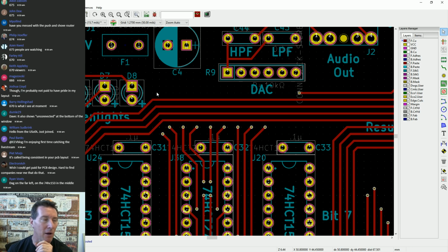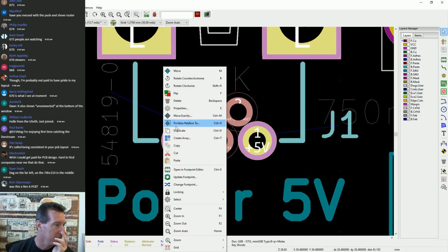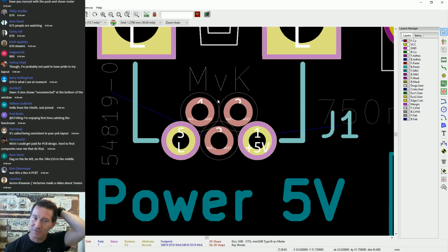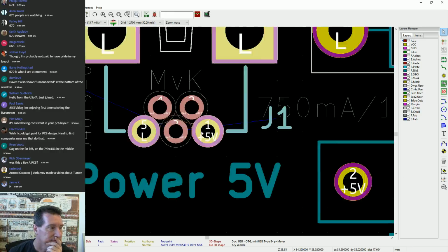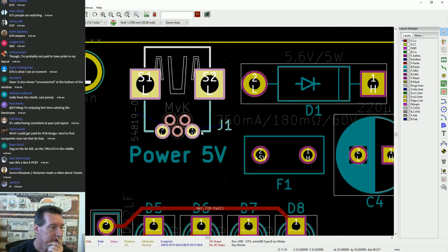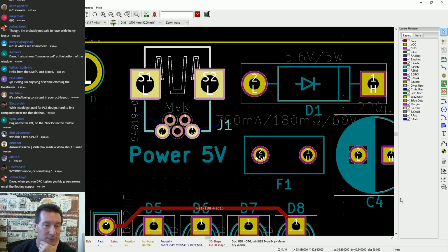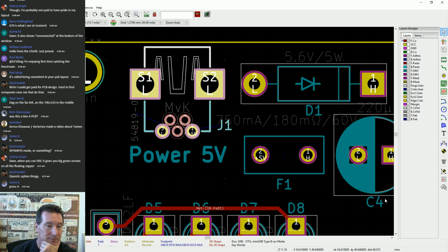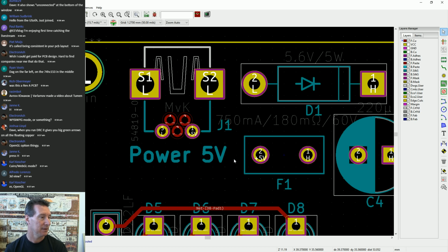Oh, what's that mode that makes KiCAD look visually perfect or whatever? What is the, if anyone knows what I'm talking about? I did it in the previous video and I completely forget. Yes, the what you see is what you get mode. Yeah, OpenGL, press H. I think that's it. Is it?